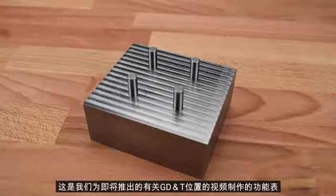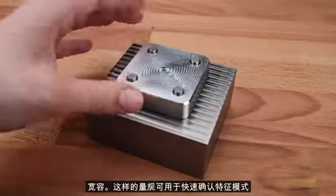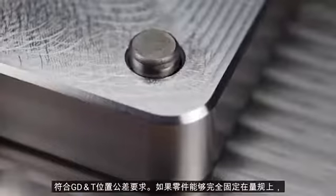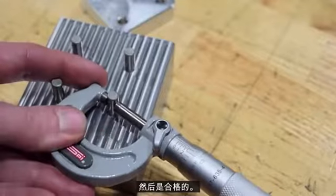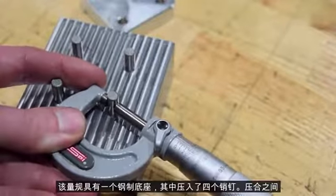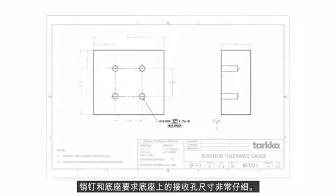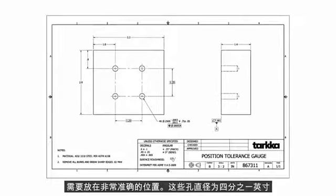This is a functional gauge we machined for an upcoming video about the GD&T position tolerance. Gauges like this can be used to quickly confirm that patterns of features meet GD&T position tolerance requirements. If the part is able to fully seat on the gauge, then it's in spec. This gauge features a steel base with 4 pins pressed into it. The press fit between the pins and the base requires the receiving holes in the base to be very carefully sized. And since the point of this part is to be a precision position gauge, the pins also need to be in very accurate locations.